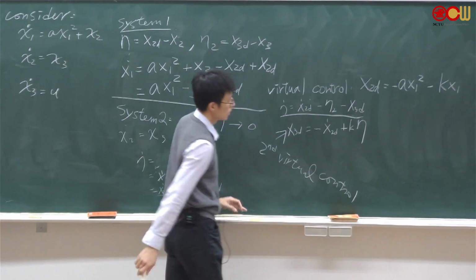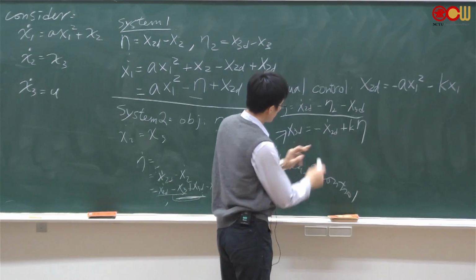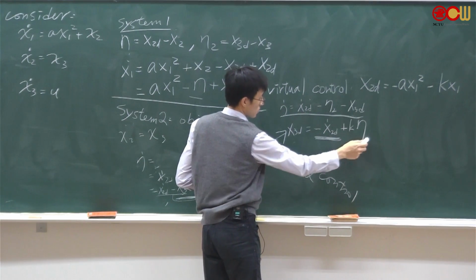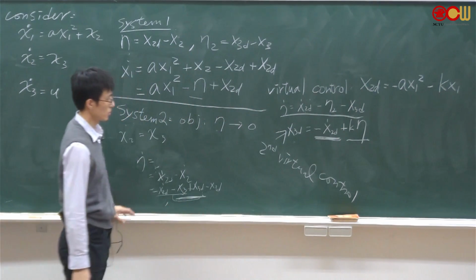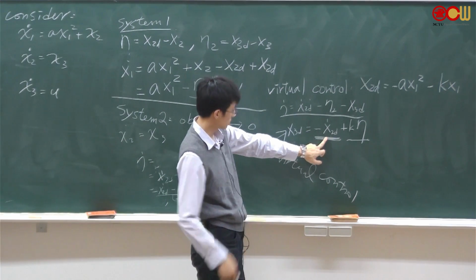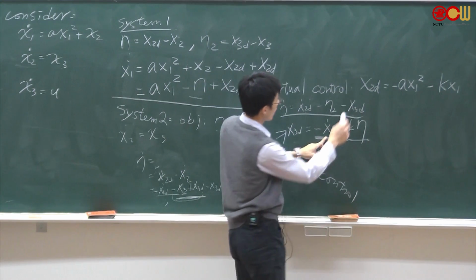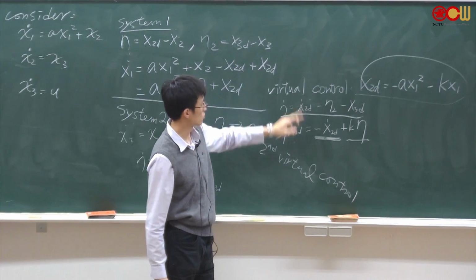So this equal to this. And x3d is the virtual control. And that can be designed as 2 terms. This term is used to cancel out this. This term is for feedback. And this term, just let it be because it's cross term. And x2d dot is the time derivative of desired trajectory, which means you need to take time derivative on the first virtual control input.